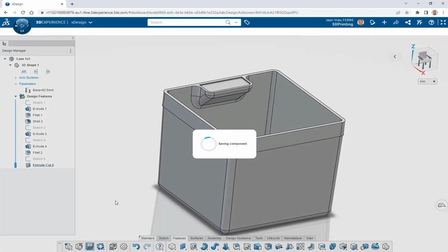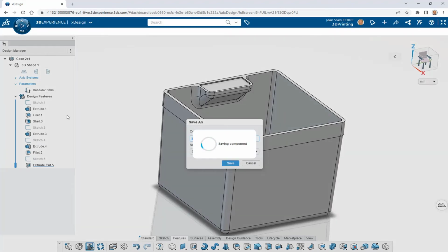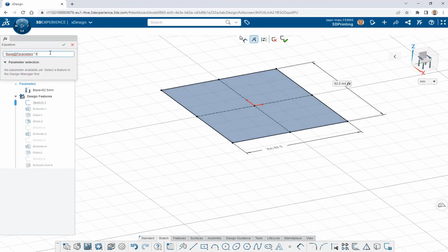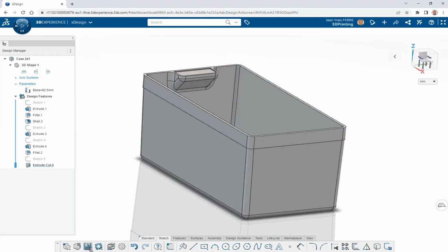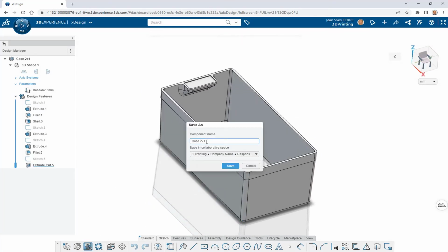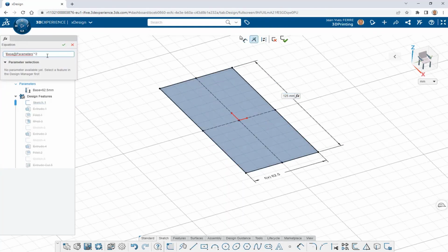So far I have created a box of 1x1 adapted to my drawer. Now let's create some other sizes with simple changes. After saving the part, I go back into the equation to change the factor and create the 2x1 model. As everything is fully defined, update runs smoothly. That's the main reason why we fully defined every sketch and every geometry. See how it's easy to create 2x1 and 3x1 in a couple of seconds.